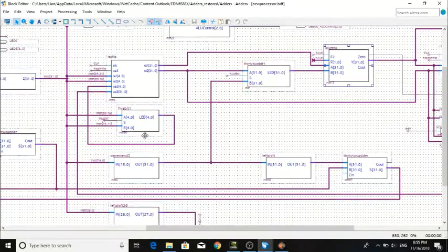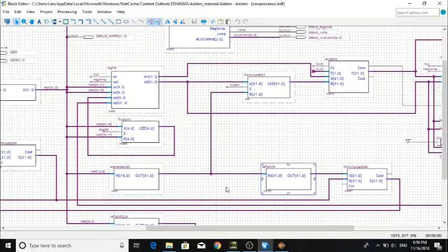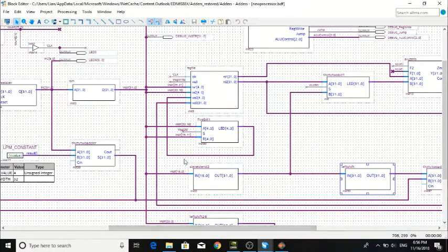This is done through sign extend, which is here at bit 15 to 0. It is then multiplied by 4, which is done through the shift left function, which on our project is called left shift. If the 2 inputs are found to be different, the program counter is just set to program counter incremented by 4.